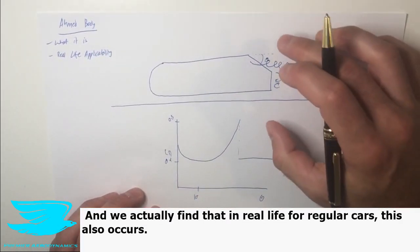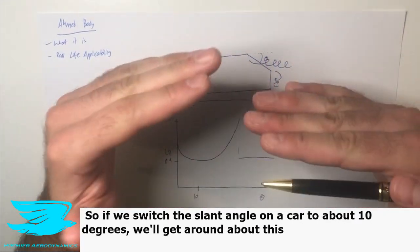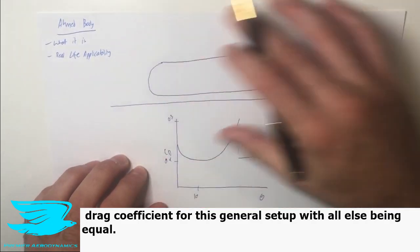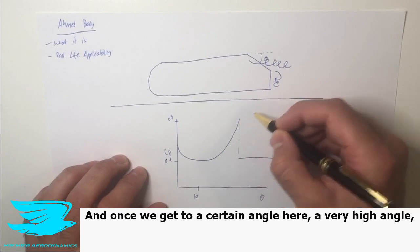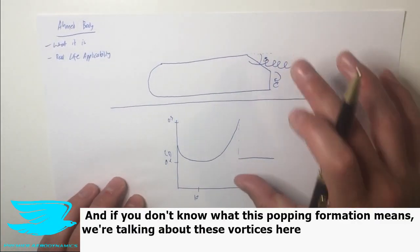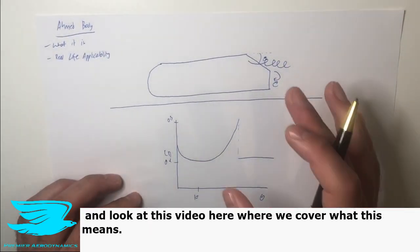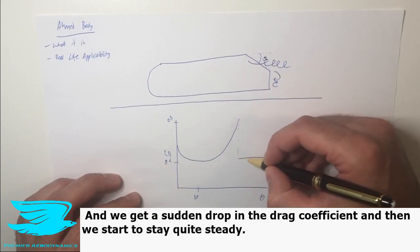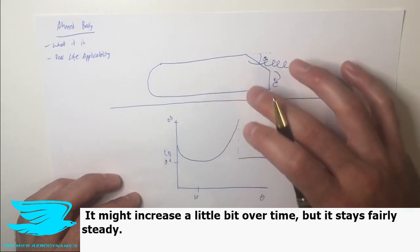And we actually find that in real life for regular cars, this also occurs. So if we were to put the slant angle on a car about 10 degrees, we'll get around about this lowest drag coefficient for this general setup, with all else being equal. And once we get to a certain angle here, a very high angle, we actually get this popping formation. And if you don't know what this popping formation means, we're talking about these vortices here, and look at this video here where we cover what this means. And we get a sudden drop in the drag coefficient, and it starts to stay quite steady. It might increase a little bit over time, but it stays fairly steady.